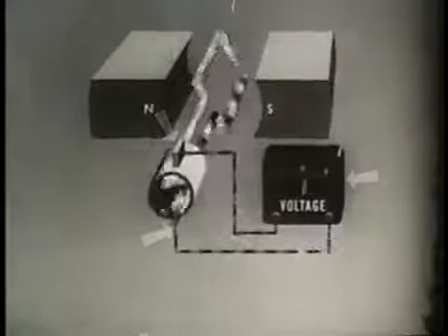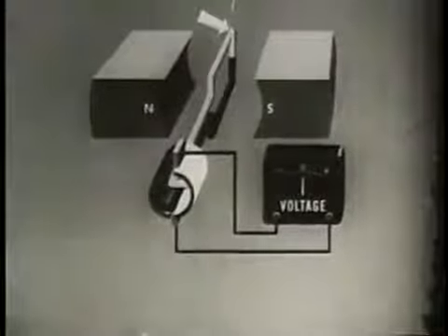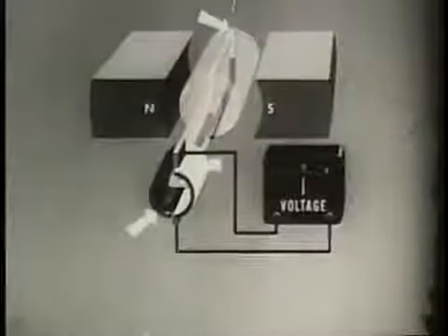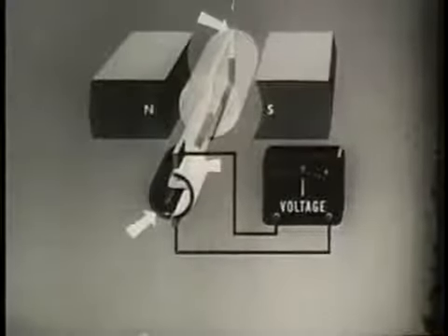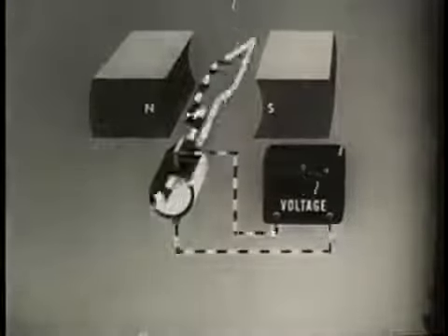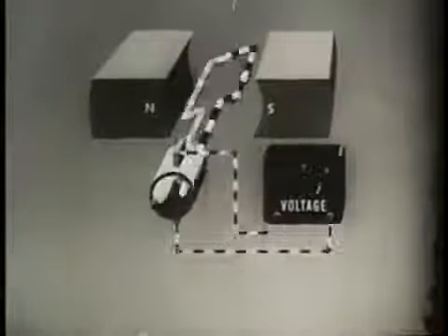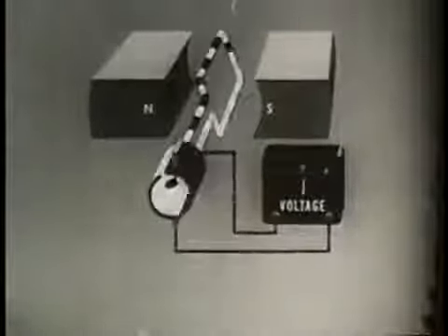The loop of a conductor, wound on a rotor, and the commutator are referred to as the armature. As the loop revolves and the EMF in the conductor reverses polarity, the connections to the load are also reversed, and the current flow will maintain the same direction externally.